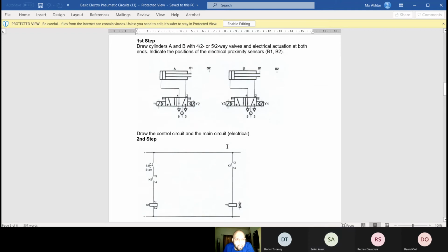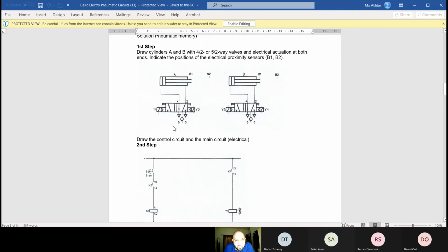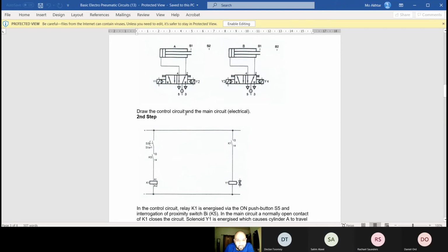So that's basically that. Maybe you drove this type of circuit, exactly this, in fact, okay? Forget K5 for the time being. You don't need that. So you've got your start button here, and then that could be an output from a PLC, like Q0.0. When that's on, then do that.